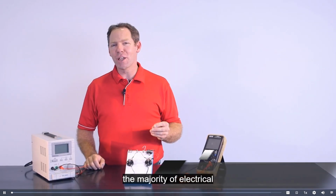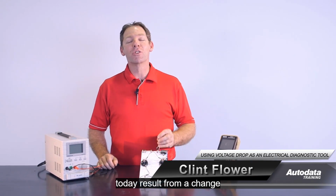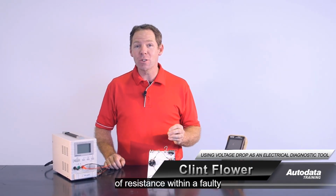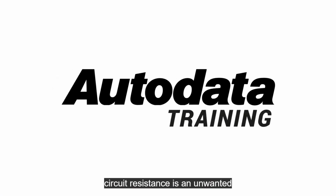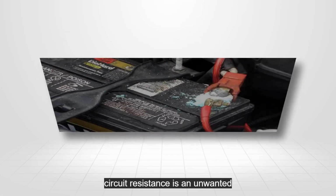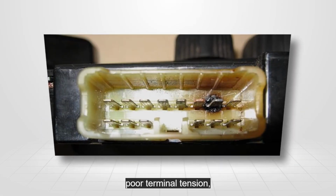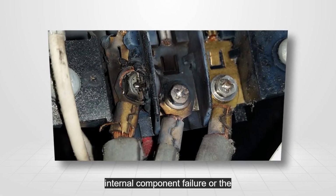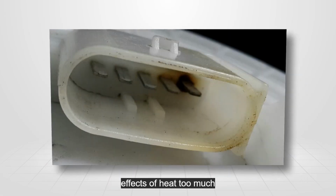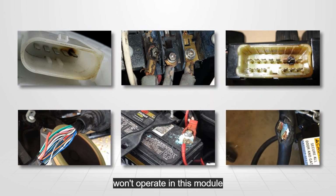The majority of electrical faults faced by automotive technicians today result from a change of resistance within a faulty circuit. Resistance is an unwanted problem caused by corrosion, poor terminal tension, internal component failure, or the effects of heat. Too much resistance and the circuit simply won't operate.